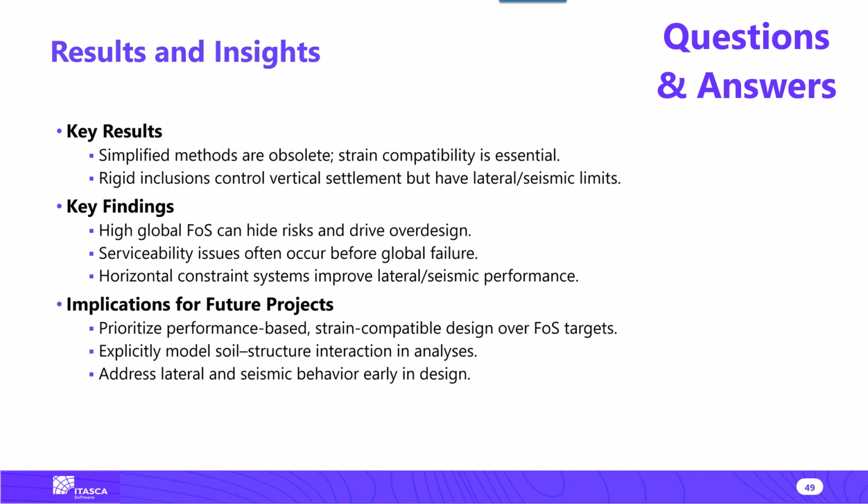And then from the unloading-reloading to get the E50, I tend to divide by, let's say, 2.5 to 4, again depending on what type of material we are talking about. The higher the soil behavioral type, the higher the number that I use to divide the property, starting from the Gmax or Emax to E unloading-reloading to E50. And then there is a separate conversation for the oedometer. We didn't touch much on that.